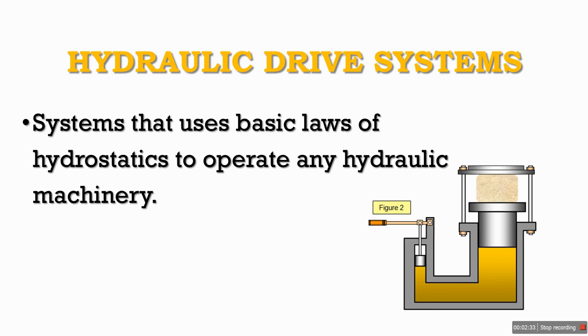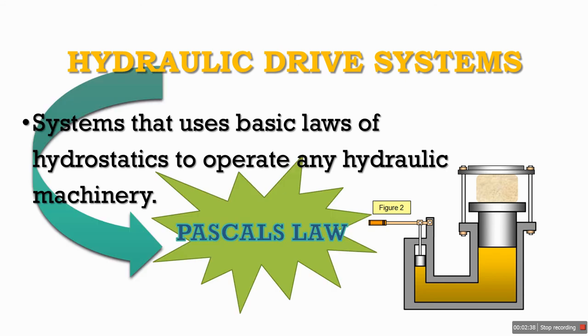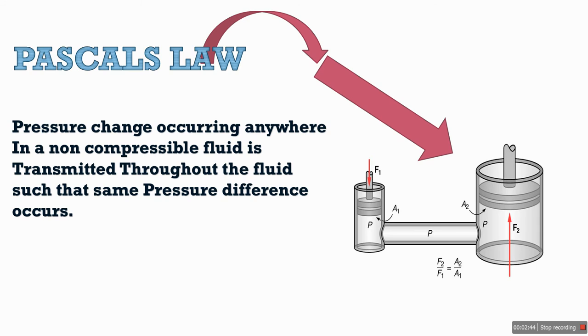One of the basic laws that govern the working of these hydraulic drive systems is Pascal's law. Pascal's law states that a pressure change occurring anywhere in a non-compressible fluid is transmitted throughout the fluid such that the same pressure change occurs. Pascal's law generally states this for non-compressible fluid, but we can also use it to some extent for compressible fluid. I'm not saying that it is 100% true for compressible fluid, so it will be like 50%.